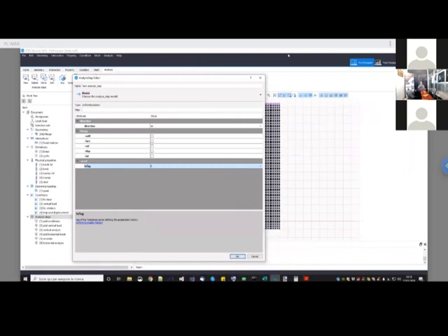Do you have any suggestion for the equivalent continuum for masonry? Particularly, is there any material that can be used with a simple mesh? I was wondering if there is a material that can be used to model together masonry and mortar. Also, how can gap links be added? Just a second, let me answer Raffaele De Risi. Of course, you can use the same material model that we have used for the microstructural components for the entire masonry. The only problem is that that material model is isotropic.